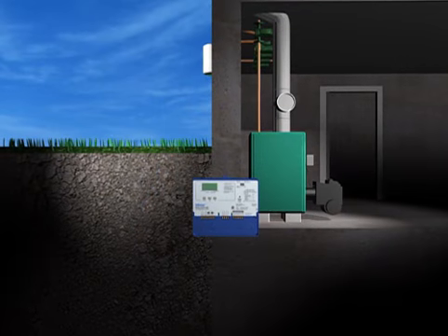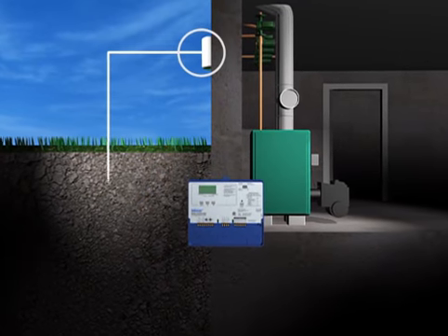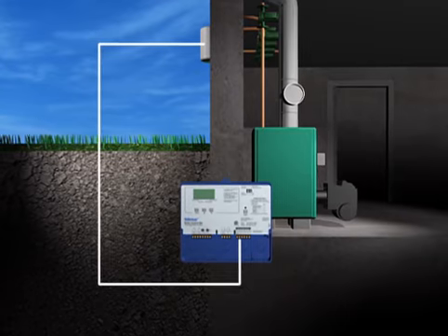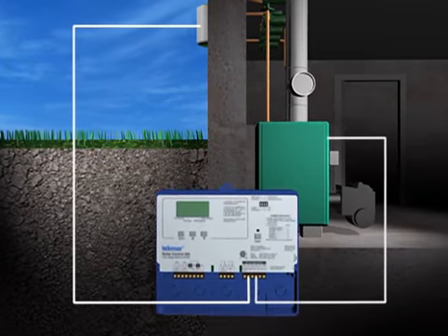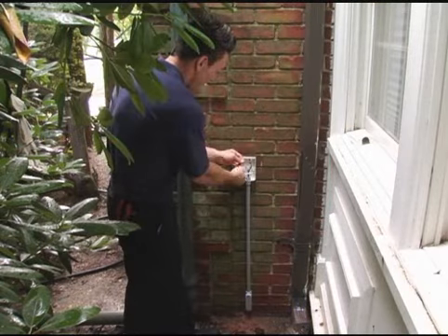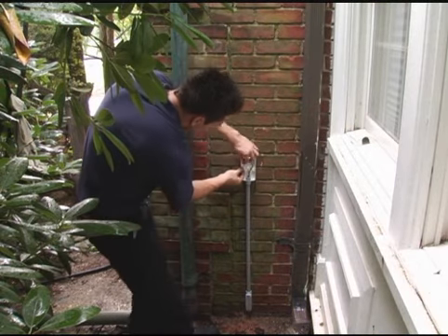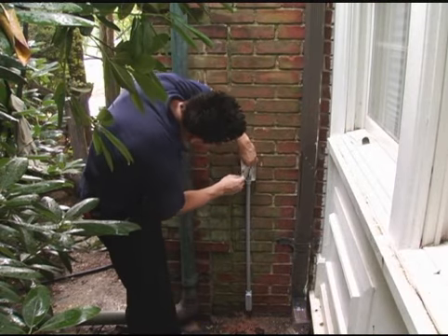With today's technology, we can use microprocessor controls that monitor the outdoor temperature and calculate appropriate boiler supply temperature to provide the correct heat input to the building. The outdoor reset control receives information about the outdoor temperature from an outdoor sensor and information about the boiler temperature from a boiler sensor. The location of these sensors is very important to ensure the control gets good information.